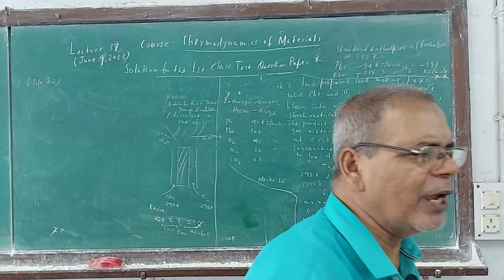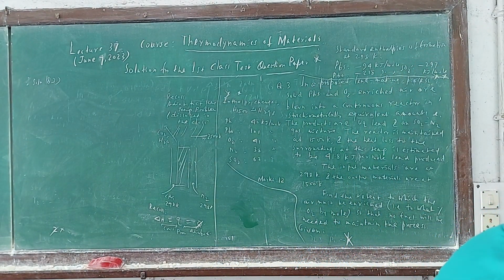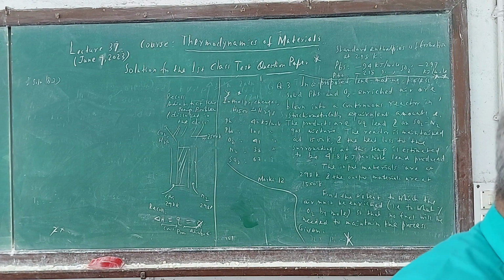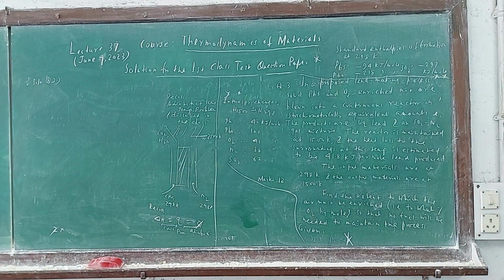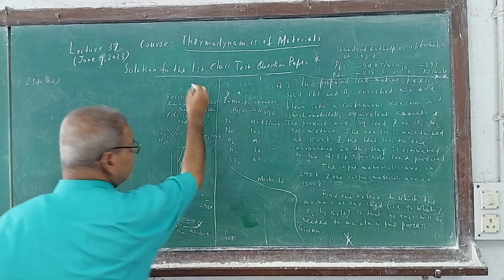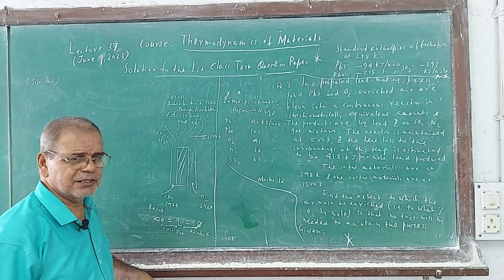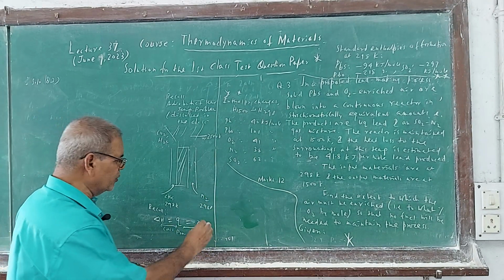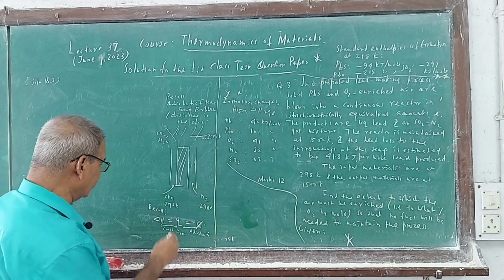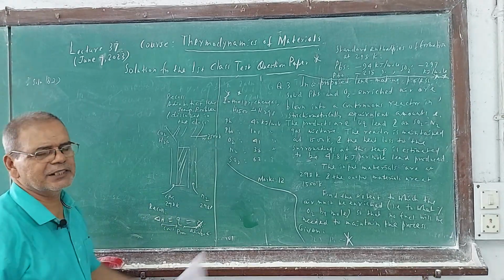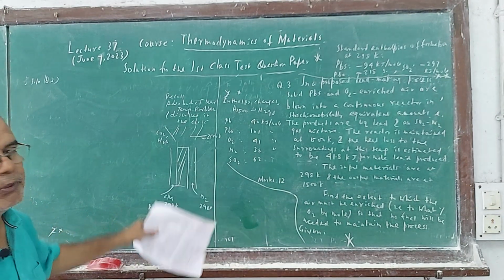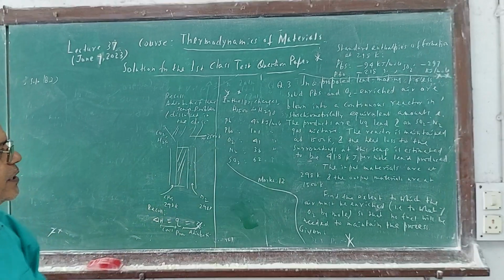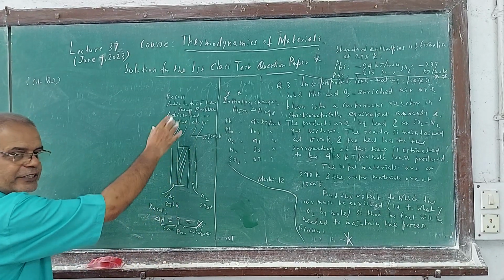Why no loss? What is adiabatic? No time to exchange. It is open, good, but so fast, no time to dissipate to the surroundings. One stream keeps coming, doing this and leaving, again coming, leaving. So this is a continuous reactor, continuously the flame is burning. So it is 0 loss. If there is a loss, put that loss, and since it is exothermic, it is giving out, so the loss is actually minus. Then it will be less than that. This is the problem I wanted to compare with. Constant pressure, this is actually continuous, meaning open to atmosphere. This is a continuous reactor.